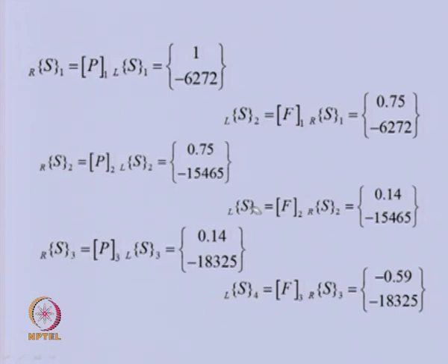Intermediate transfer matrices can be used to obtain the relative displacement. So, the first term is the displacements. They can be extracted to obtain the relative displacements of the various disks, and that can be plotted as a mode shape.